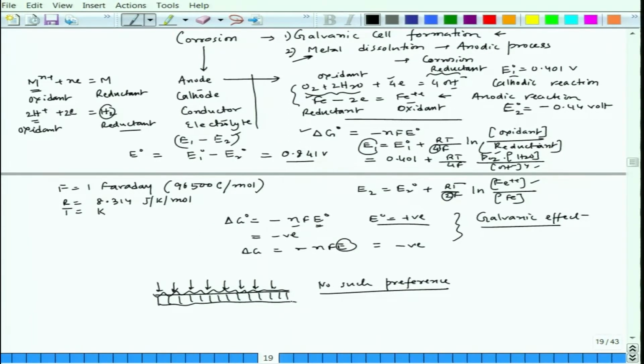So, that is what we call uniform corrosion. So, galvanic uniform corrosion from the fundamental mechanism point of view is actually galvanic corrosion if we consider the electrochemical reaction part, but since it is happening over the entire surface without any localized positioning of cathodes or anodes, that is what we call uniform corrosion.